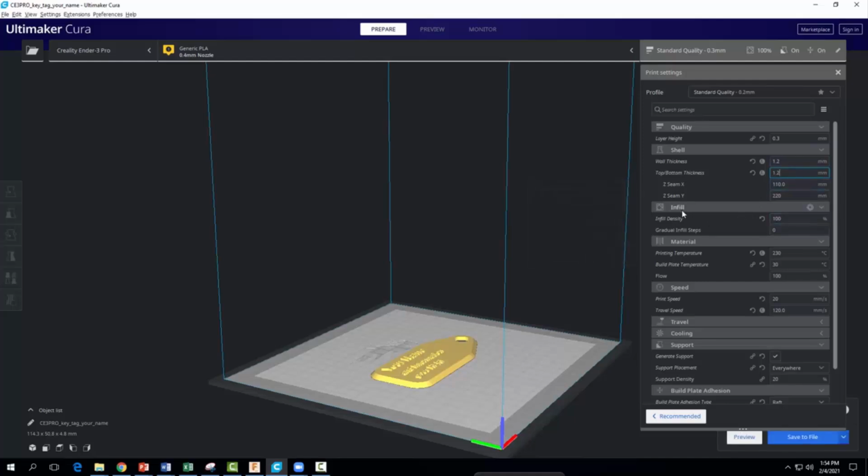And then our infill density. Infill density is 100% if we want to make the object completely solid, which isn't very practical, and it will make your print times, once again, extremely long. So I recommend an infill density for most objects, unless you need a lot of strength, typically between 15 and 30%. I'm going to go ahead and select 20 for this object.